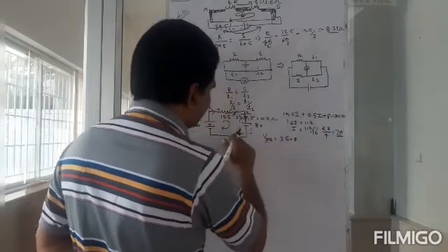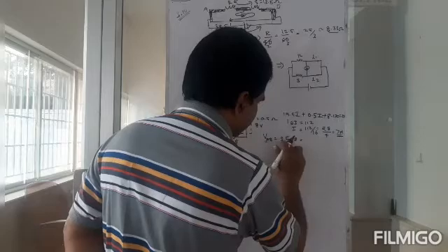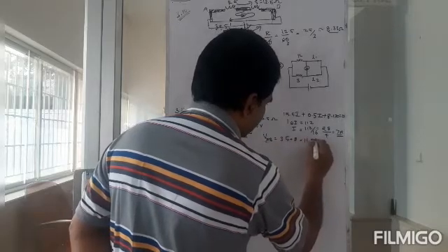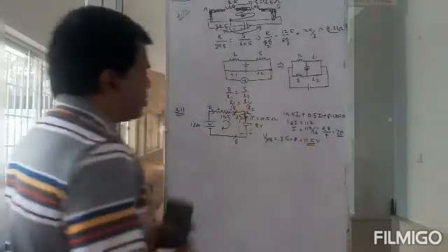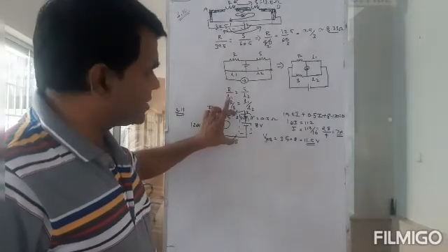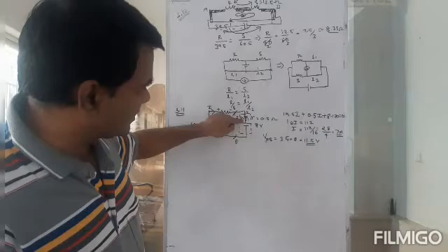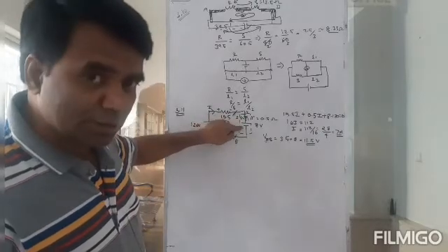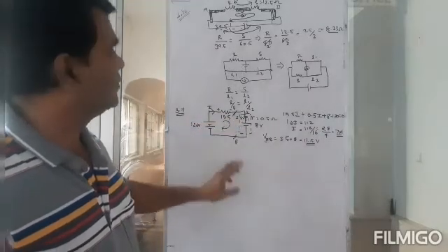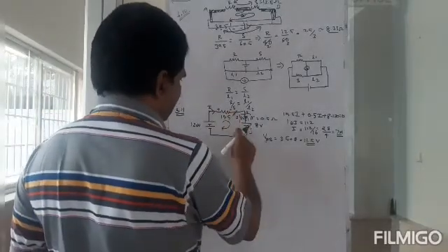Okay, then I come here. So that is going to be 11.5 volts. So to charge an 8 volt battery, the terminal voltage must be 11.5, so that there is a drop of 3.5 across this resistor, and the remaining 8 volts would be used to charge this battery. So I can do it this way, or I can do it this way also.